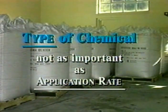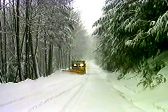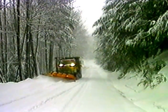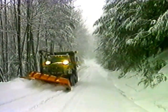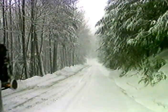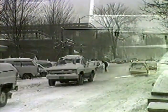Experience and studies suggest that the anti-icing chemical itself may not be as important as the application rate. To reduce chemical dilution, snow or loose ice should be plowed off the road before applying chemicals. This is good practice anytime chemicals are applied, but is even more important when liquid chemical solutions are used alone. Excess snow and ice will require more chemical to achieve an effective concentration.